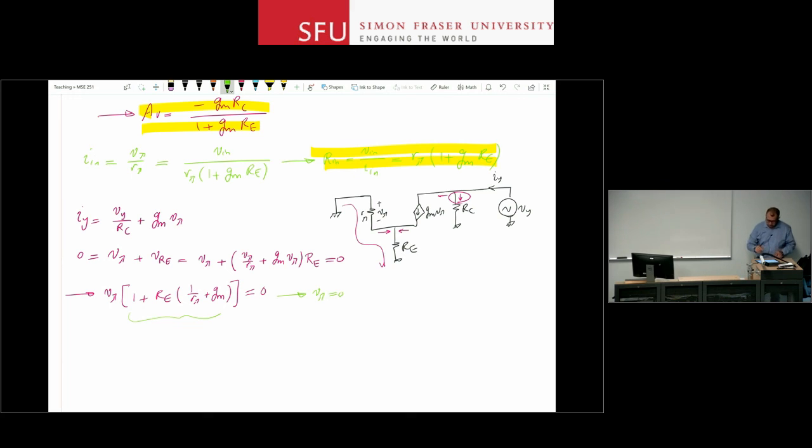Well, this is the reason. You have applied a voltage source above a current source. Whatever changes voltage in voltage that you have here, the current source doesn't care. The current source can take any voltage across it. So all the changes of the voltage here will not affect the current through the current source here.